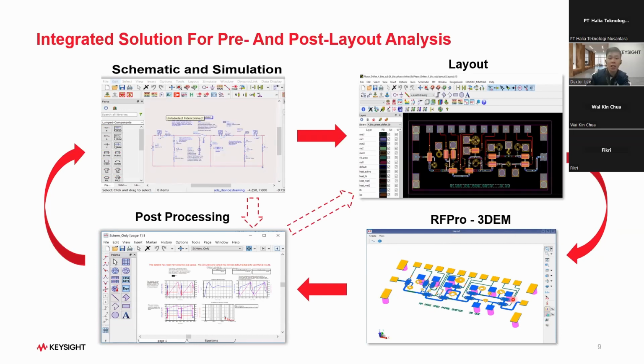So once you finish the EM simulation setup, that's where you run or export the EM simulation results back to the schematic test bench. Either do S parameter simulation results again with your EM simulation, or harmonic balance, or simulate it with a 5G signal. You are then able to look at the results through our data display.